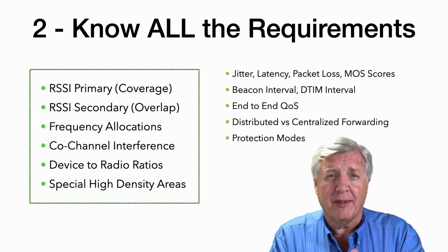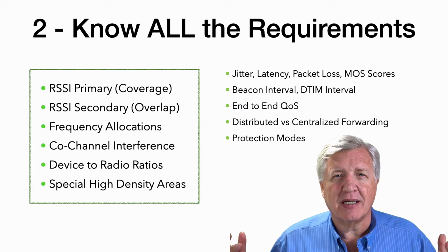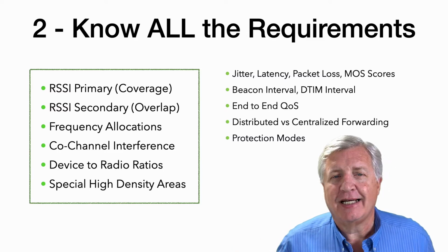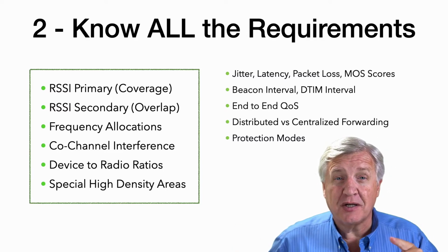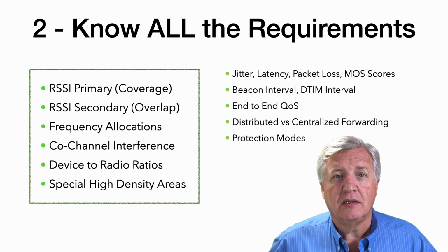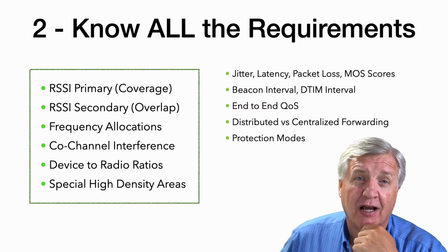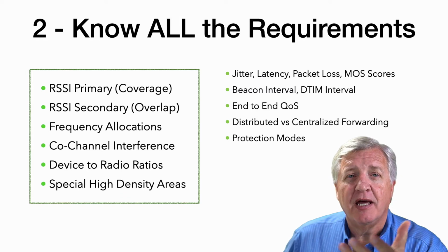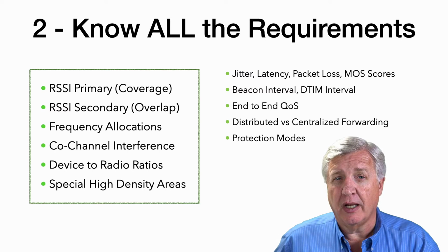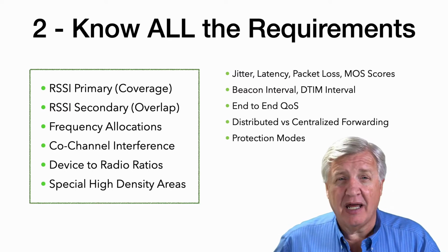There's a whole lot of requirements, and we usually get a requirement from our customers who come in and say something like, we just need the Wi-Fi to work everywhere fast. Yeah, it doesn't work that way. Not to mention, we can't design Wi-Fi for all Wi-Fi clients. Just as an example, iPhone 1 had Wi-Fi. Now, if you were going to design to make it efficient for an iPhone 1 today, you're designing for 2.4 gig, not for 5. And that's just one thing. It had a bad antenna, the bad chipset.